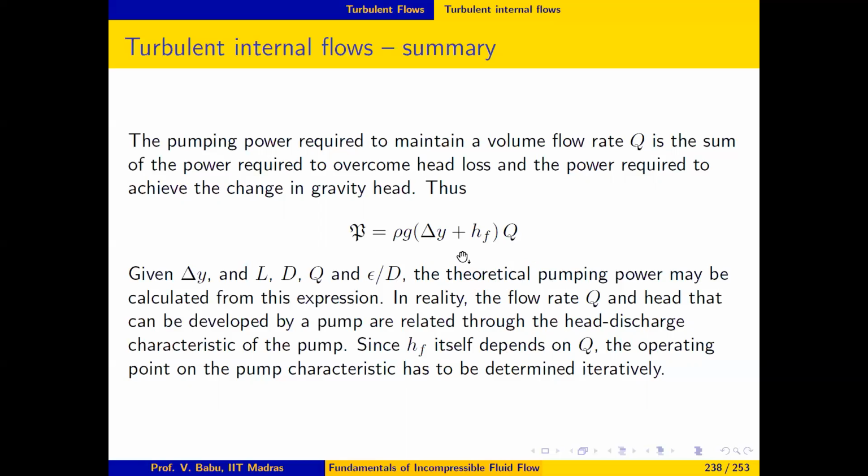The efficiency of the pump is also usually available from the pump characteristic. So this is the theoretical power. We can then divide this by the efficiency of the pump to get the actual power that is required to accomplish the stated objective.